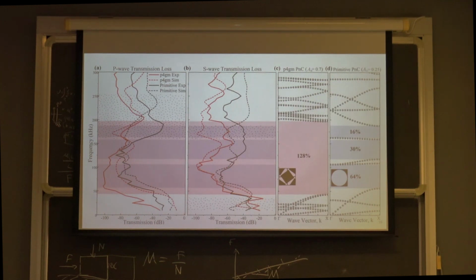So we have pretty good agreement for both structures. Another interesting thing that we noticed is that the P4GM phononic crystals damp waves more than the P4MM crystal. So not only is the band gap size bigger, but also the actual attenuation is bigger. And if you notice, it's close to 1 dB, which is actually the noise floor of our setup, meaning that these P4GM crystals can be handy in cases where you need to completely eliminate the signal. So almost kill it.